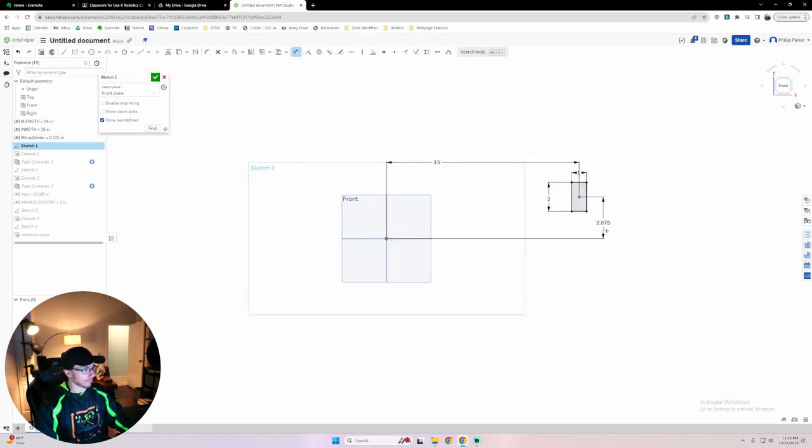All right. Notice how I did an equation in there. You can do that sort of stuff. You can do 3 inches minus drop center, and notice I had to define each half of it. It knew that the variable was in inches, but I had to define that the other number was also in inches. Okay, and then I'm going to press OK.